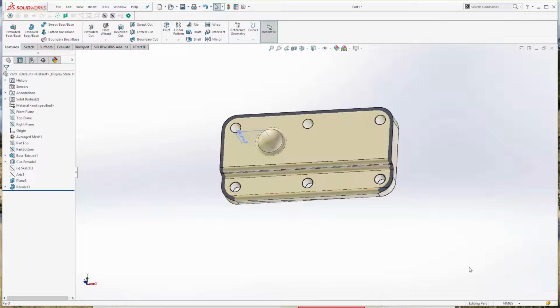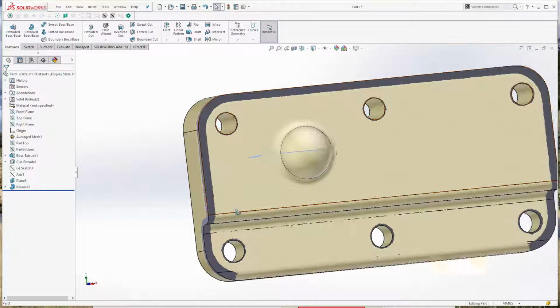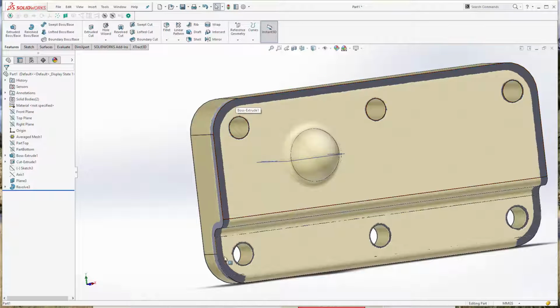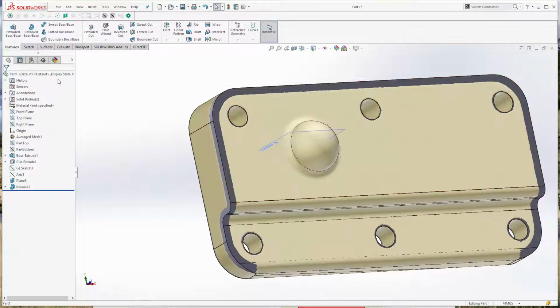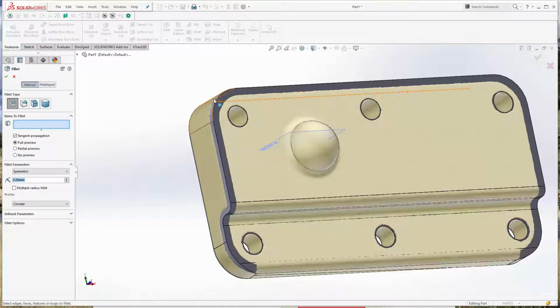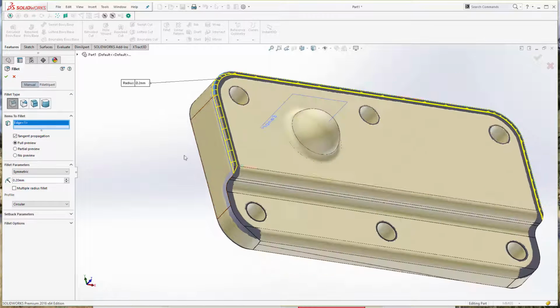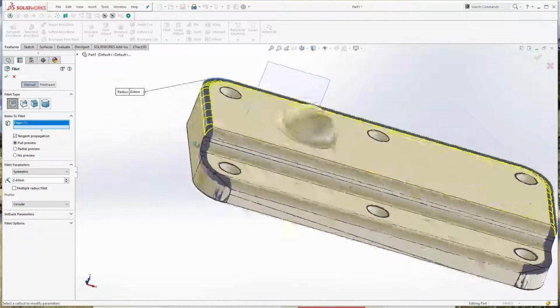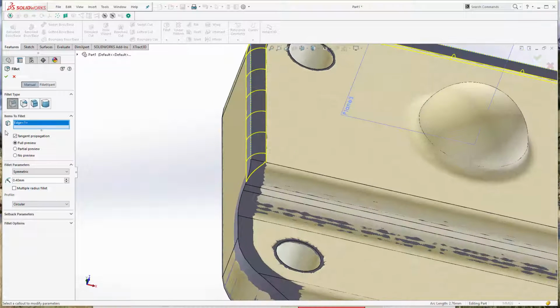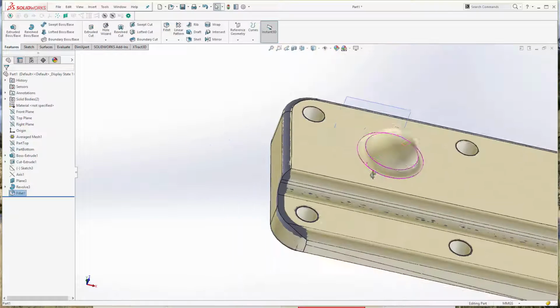So in the interest of time, and also being able to show off some of our comparison tool, what I'm going to do is, instead of finishing these off, I'm going to do a manual fillet of these edges by hand instead of referring to the scan data. So what I'll do is start my fillet tool. Just grab this edge. So let's see. I'm just going to choose a value that just happens to look good. So I'll fillet it by 0.4.